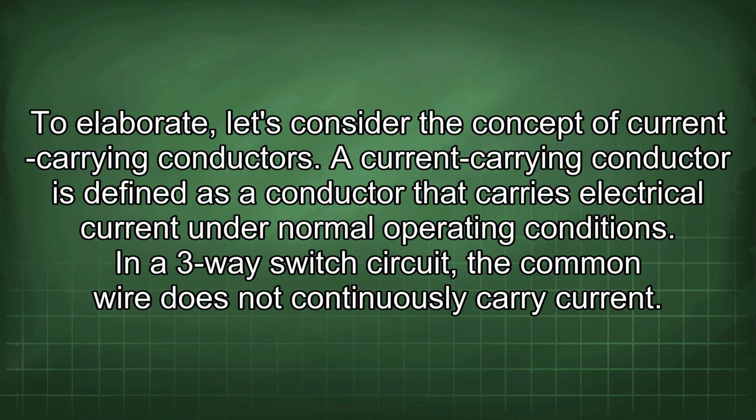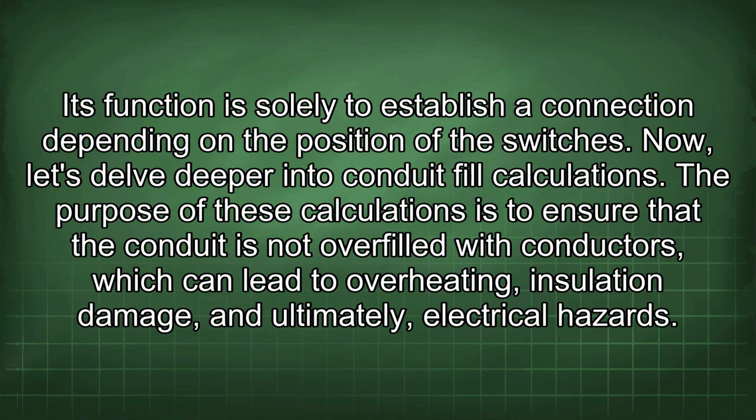To elaborate, let's consider the concept of current-carrying conductors. A current-carrying conductor is defined as a conductor that carries electrical current under normal operating conditions. In a three-way switch circuit, the common wire does not continuously carry current. Its function is solely to establish a connection depending on the position of the switches.